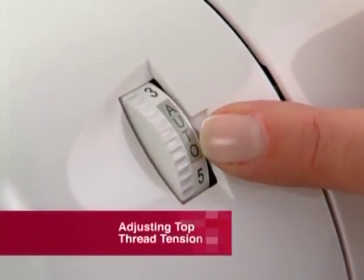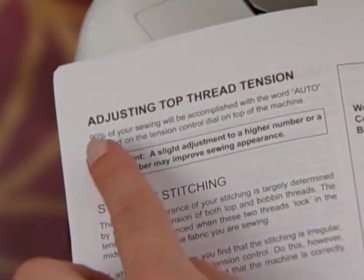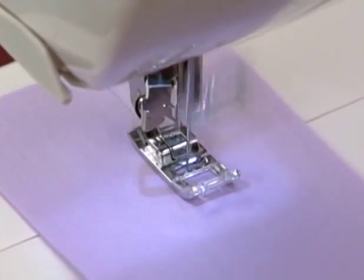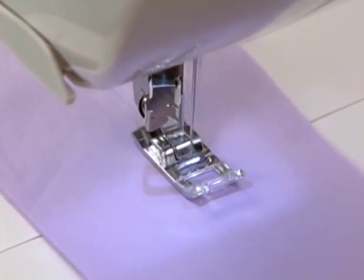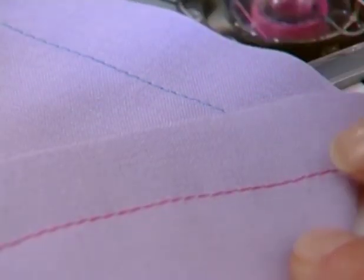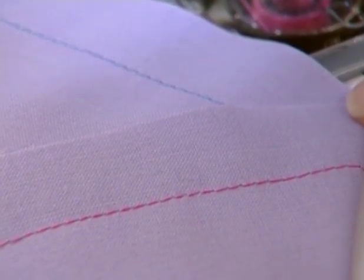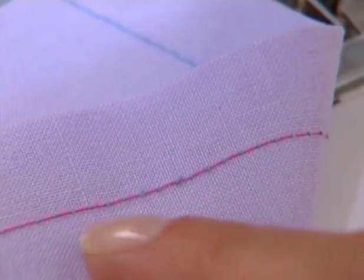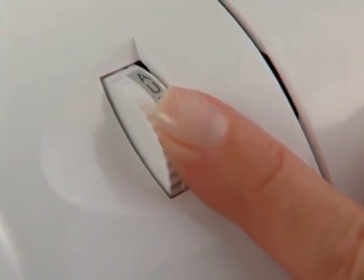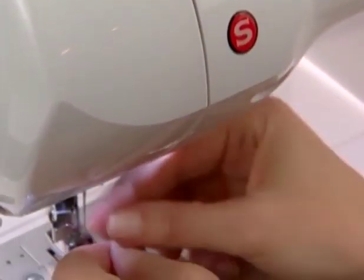90% of your sewing will be done with your tension control set in the normal or automatic range as indicated by the instruction manual for your model of machine. The correct appearance of your stitching is mostly determined by the balanced tension of both top and bobbin threads. For straight stitch sewing, the tension is well balanced when these two threads lock in the middle of the fabric layers you are sewing. If, when you start to sew, you find that the stitching is irregular, you will need to adjust the tension control. Do this, however, only after you have determined that the machine has been correctly threaded.